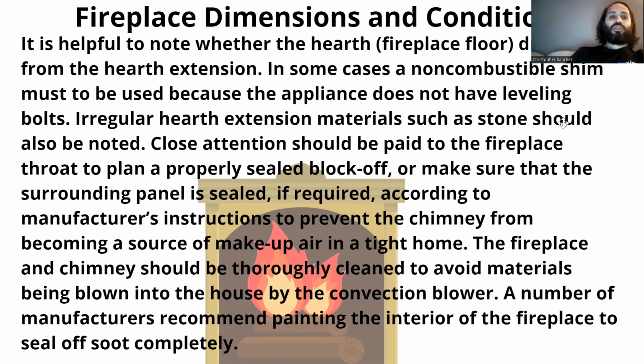Close attention should be paid to the fireplace throat to plan a properly sealed block off or make sure that the surrounding panel is sealed, if required according to manufacturer's instructions, to prevent the chimney from becoming a source of makeup air in a tight home. The fireplace and chimney should be thoroughly cleaned to avoid materials being blown into the house by the convection blower. A number of manufacturers recommend painting the interior of the fireplace to seal off soot completely.